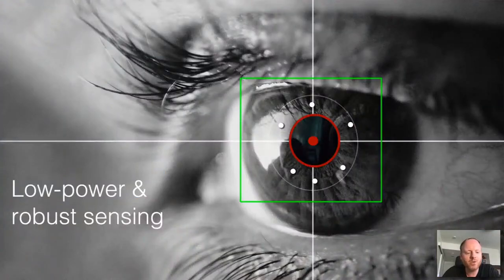And then the last thing I mentioned was eye movements. So eye movements include eye tracking, and eye tracking is something that seems like a solved area, like many in graphics, but the devil is really in the detail, and there's no real commercial eye tracking system, especially for AR, that works at the low powers required for all-day wearable use, that is robust enough to drastic changes in the environment, ambient illumination, that has the low latency that captures the eye movements at enough speed and latency to really capture microsaccades and all the subtle eye movements.